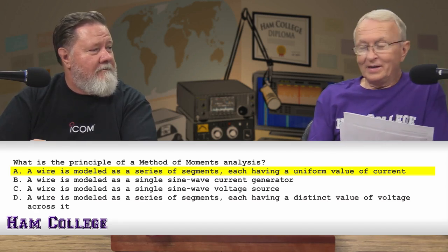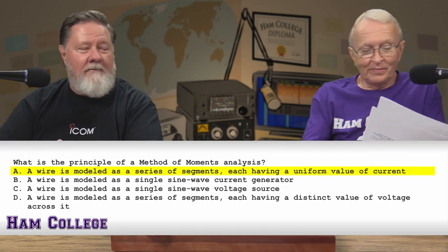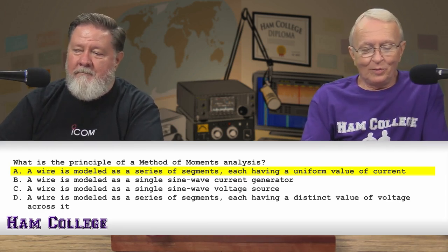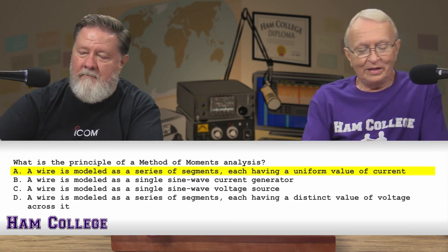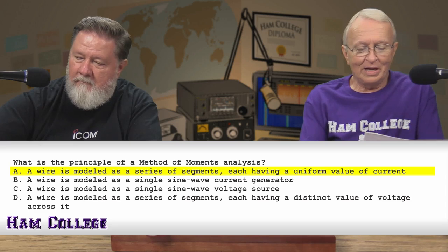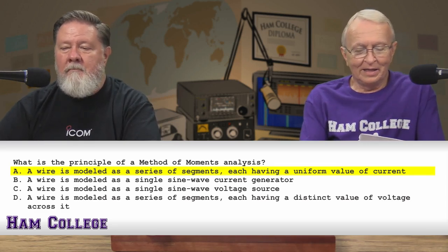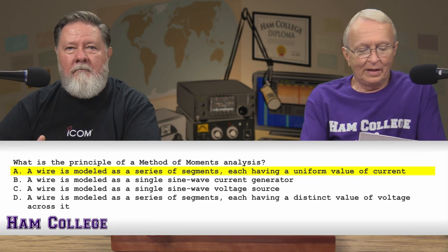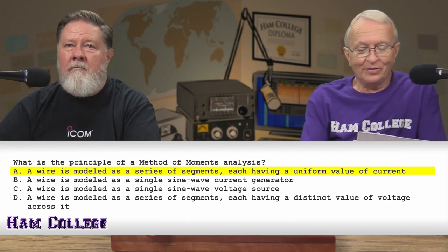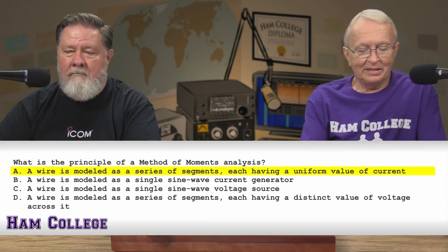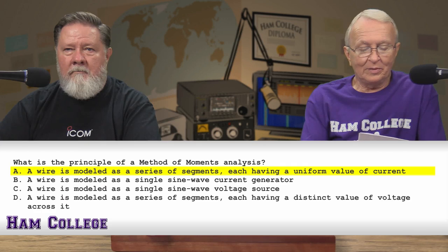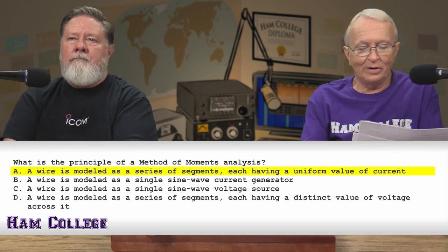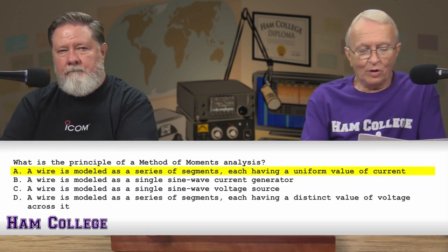I did a little study here. Here's what I come up with. The method of moments, also known as moment method and methods of weighted residuals, is a numerical method in computational electromagnetics. It's used in computer programs to simulate the interaction of electromagnetic fields. Antenna simulation programs like NEC calculate the radiation pattern of an antenna. Generally being a frequency domain method, it involves the projection of an integral equation into a system of linear equations by the application of appropriate boundary conditions.